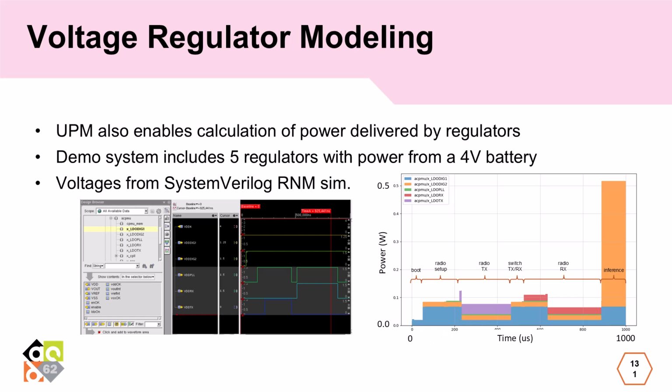One thing to point out here is that we are using the RISC-V to sequence the radio. So there's a significant amount of RISC-V power during this interval where we're waiting for the ADC to warm up. We have to keep the RISC-V alive so that it can time that interval. So this points out the need in the system for some sort of state machine to manage the radio sequencing so that we can put the RISC-V into standby and save some power.